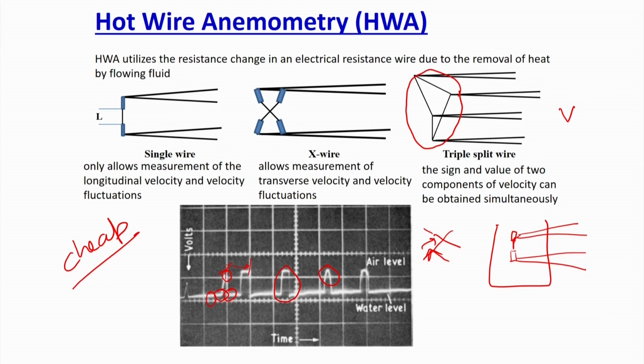So, welcome back. Last class we were discussing hot wire anemometry and the pitot tube briefly. In hot wire anemometry, I said that there is a wire, and you are connecting the wire to a Wheatstone bridge circuit. To briefly remind you what happened: there will be a wire, and once you pass a fluid the temperature will change, and because of that the resistance in the Wheatstone bridge will also change and you can detect it. Since we know the length of the wire, we can calculate the velocity.